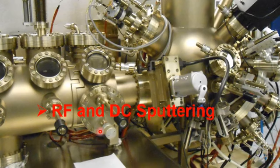So RF and DC sputtering, though advantageous in terms of cost compared to molecular beam epitaxy, in terms of quality have no comparison to molecular beam epitaxy. The film deposited in molecular beam epitaxy is highly pure and well oriented as compared to these techniques. But the advantage of DC or RF sputtering is that these techniques are less costly as compared to molecular beam epitaxy.